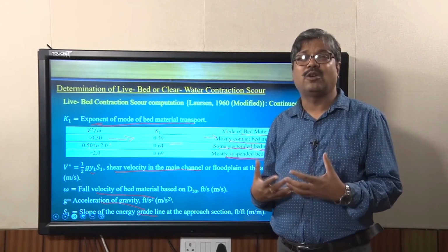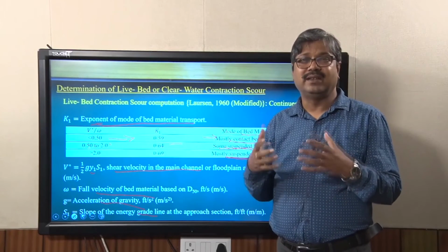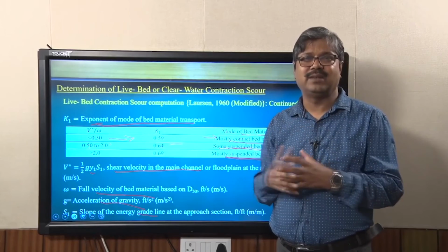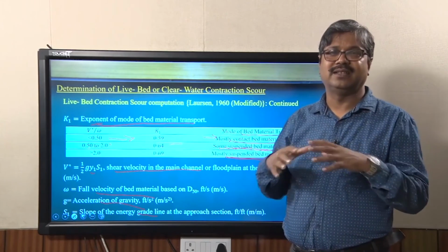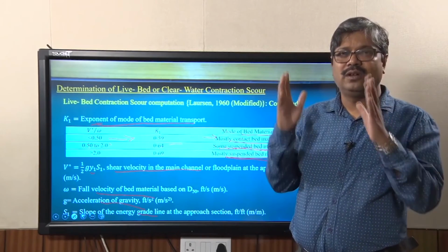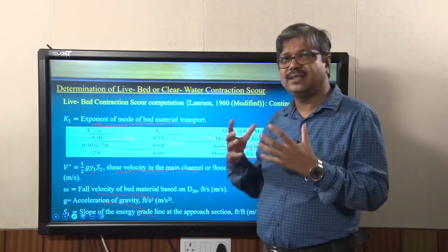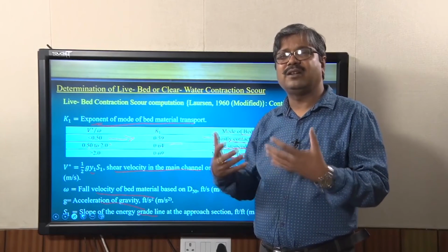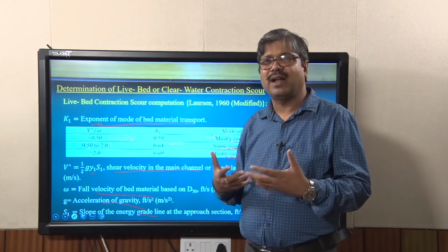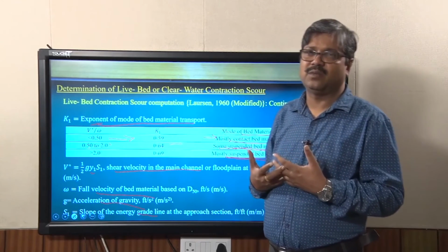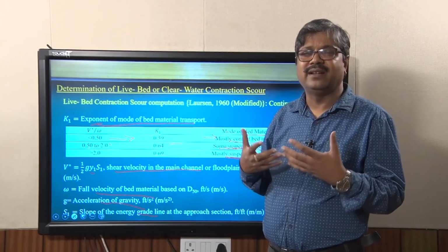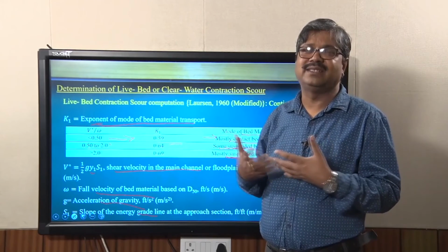When you talk about the scouring mechanisms, it is the flow interacting with the sediment transport and the structures. These are three interactions, between flow, sediment and structures. That is the reason why, after conducting a series of experiments, we get empirical equations. We may not have a physical justification for these equations, but we can try to interpret them and make them a design guideline or design skill.